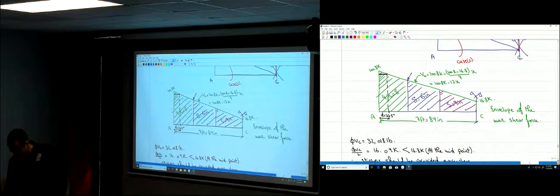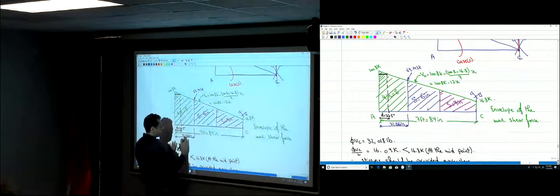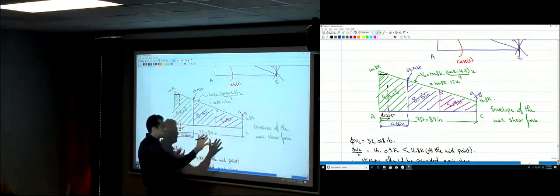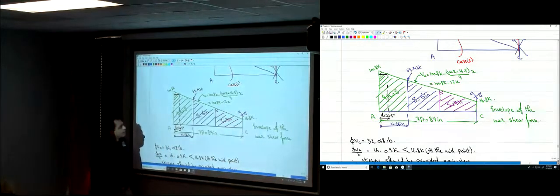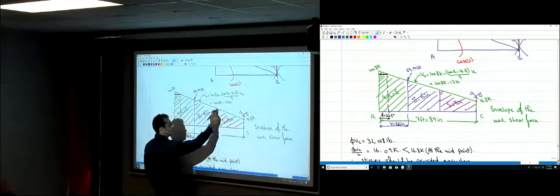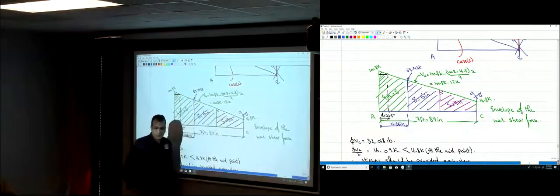So when x is 31.66, the shear, the strength, is 69.143 K, and that distance is 31.66 inches. So anywhere beyond this point, 31.66 inches, you can provide spacing of 6 inches. It's going to be enough. Okay? Now, the same. At what point is spacing of 9 inches going to be enough? I need to find the strength of 9 inches of spacing and find that point. Okay?